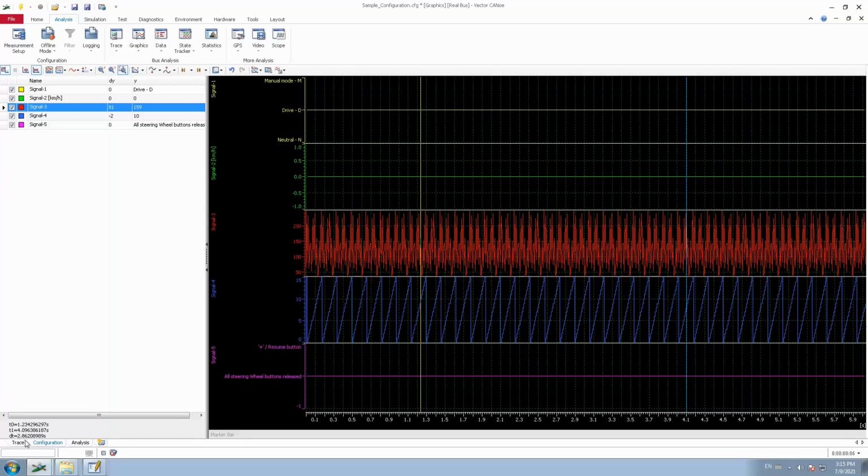So it is 2.86 seconds between cursor 1 and cursor 2. That is the major purpose of having this cursor. This is how we can do an analysis. If you have multiple transitions, you can make use of these cursor options to do a better analysis. That is the purpose of cursors.